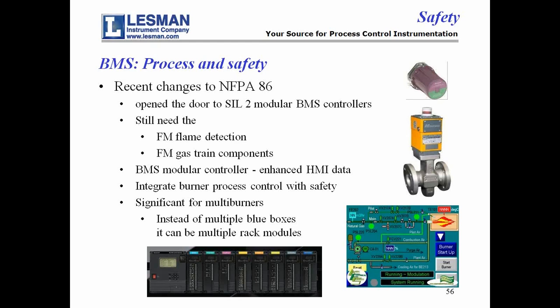The goal of all safety instrumented systems is to bring the process to a safe condition. And to do that, there are components that are either proven in use or SIL certified. And there are 3 agencies out there, FM, exida, and TÜV, that can all certify devices to have a given SIL certification on them. And those are the field devices that sit out there. And there's also controllers and what they call logic solvers that are fault tolerant and have a lot of internal diagnostics to make sure that they're actually operating properly.